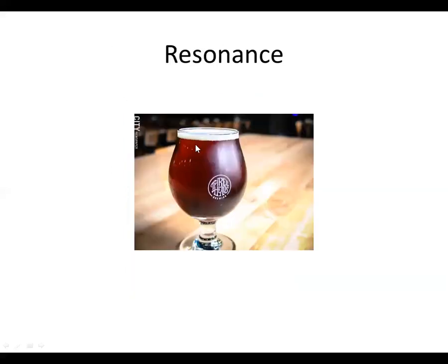But if you had an impedance setup where the reactance is almost zero, you get more of the good stuff. If you look at it from a resonance standpoint, if you're resonant on your antenna, it's where you don't have much reactance, if any.